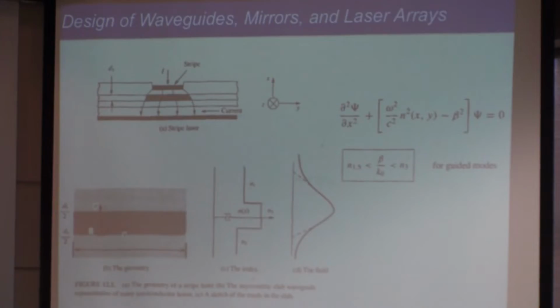This is the double heterostructure sort of laser, and therefore because of this mismatch in refractive index, the electric field of the light wave or the photon wave is going to be shaped by the refractive index. Okay. And this problem is very similar. It's a classical problem. If you have a difference in refractive indexes, how does light flow, right? And that's a classical electromagnetic theory problem.